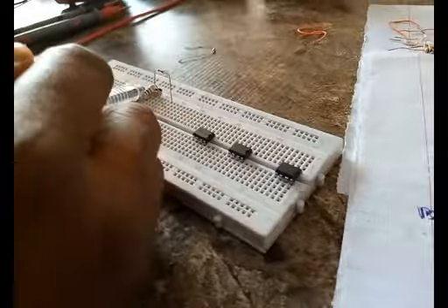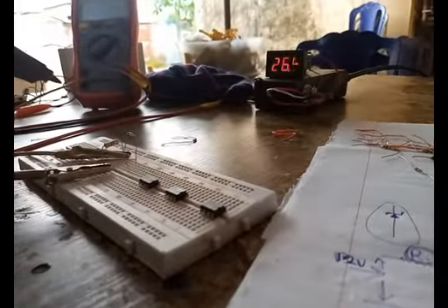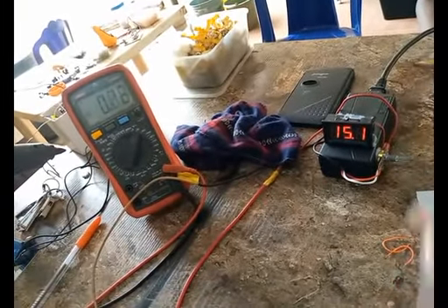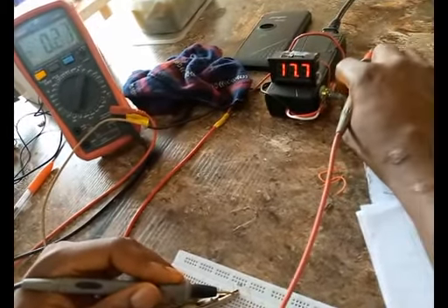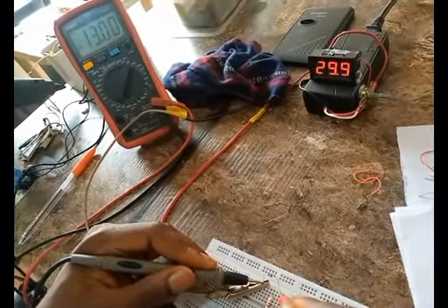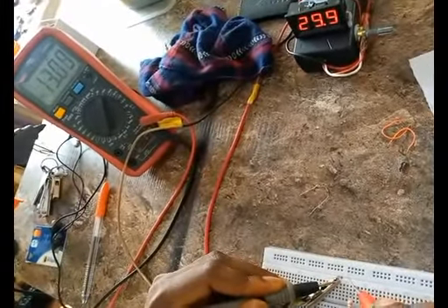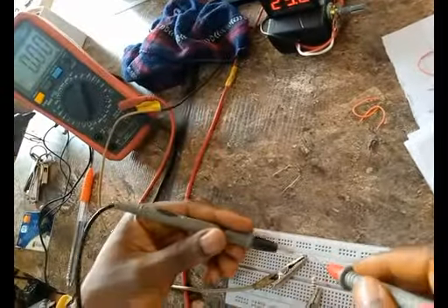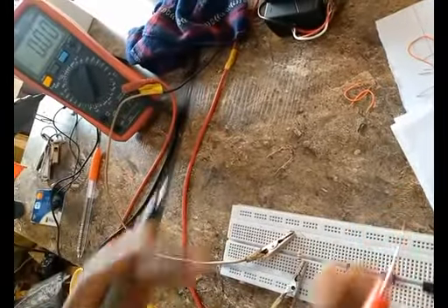Now this is half watt, and we have roughly 26 volts entering, and what we have at the output is around 12 volts. Let's drop it a little bit. It flips to around 12 volts. Now why did we have a higher voltage there, about 13? Remember, it's even still around 12 volts with a 29 volt input. The reason we have that higher voltage is there is no load at the output. Once we load the output, the voltage will still remain around that figure.